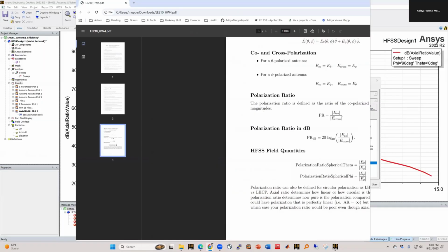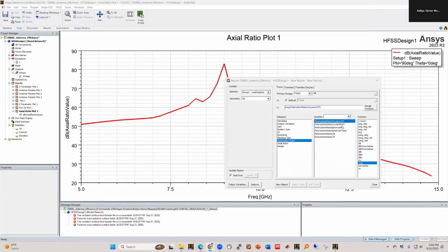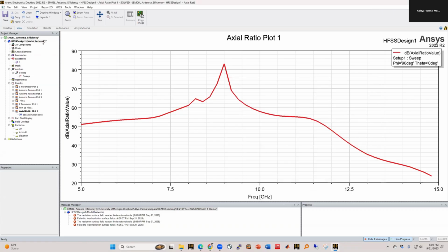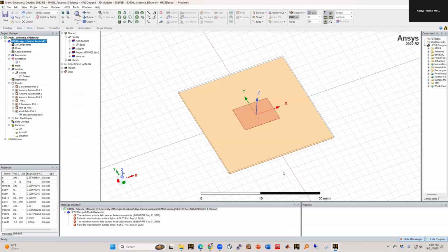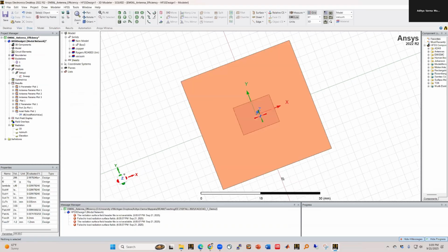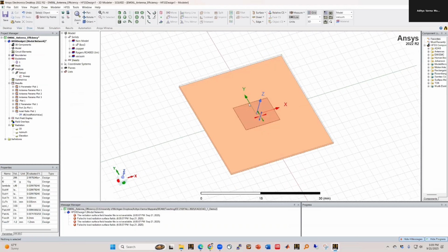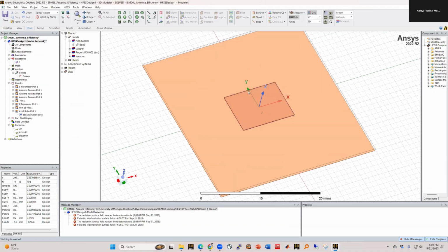Okay. All right, so going back, now we actually see that there's LHCP, RHCP, we won't bother with these right now. And there is theta and phi. So first we need to determine how our antenna is oriented and what the polarization direction is like. Right, so we have our patch antenna, and we'll see later in the class that if the patch is excited here, then the currents actually flow along y hat.